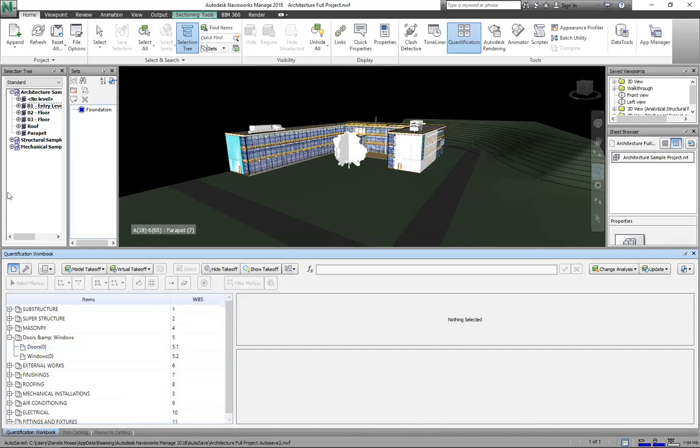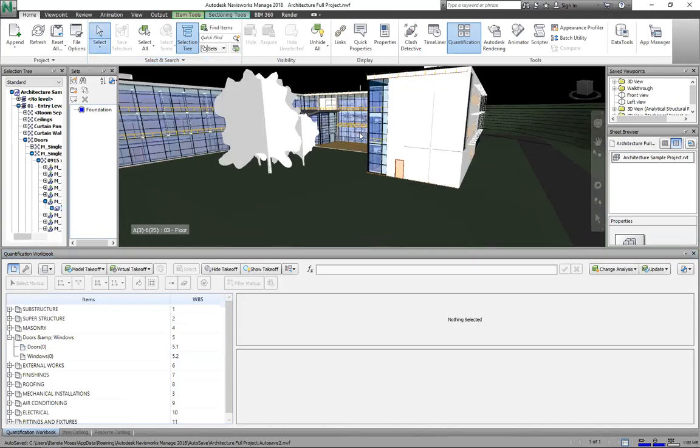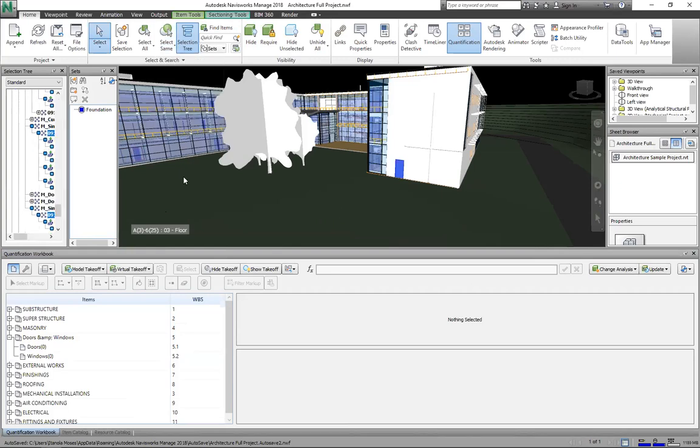So an example of this is, and of course, we might have dealt with selection with these tools, defined tools. So if I select door, this is a door here, and then say select same item. Now, if I say select same item using name, that automatically searches through all the models and selects any item that is called a door.